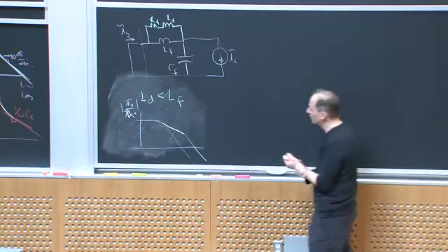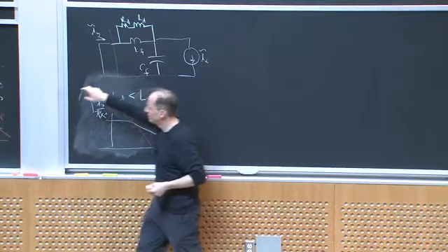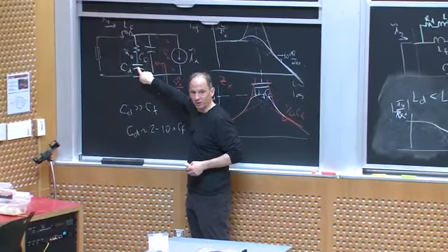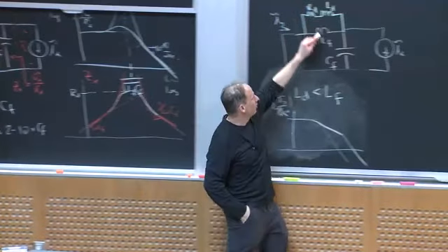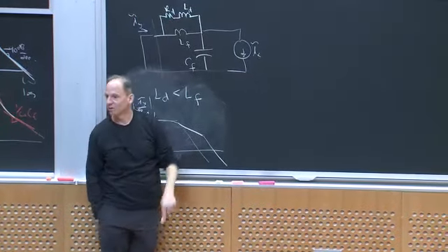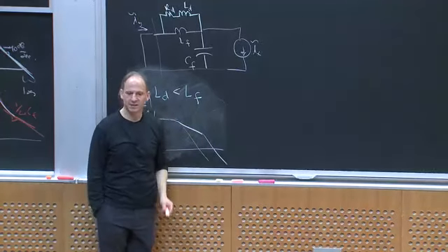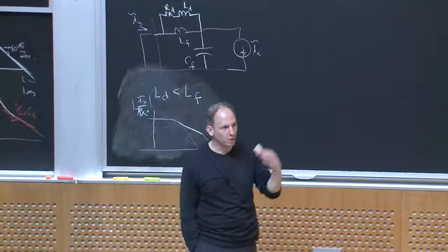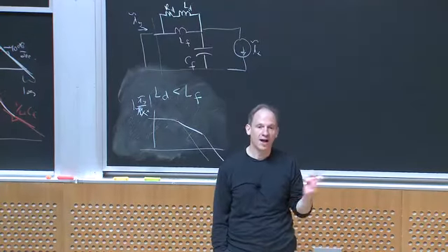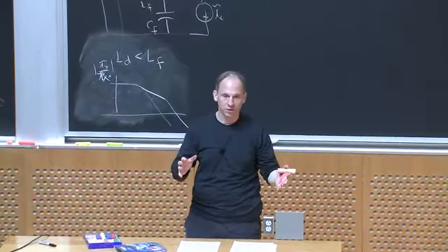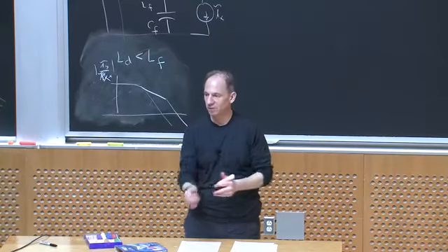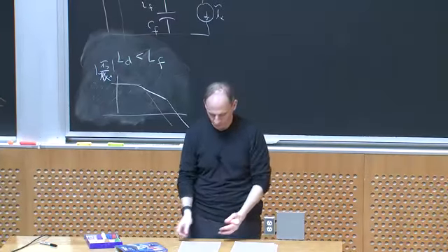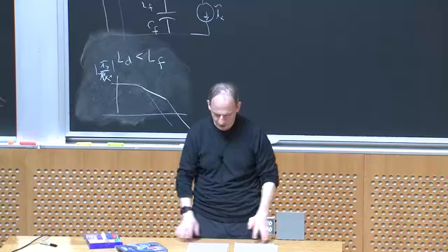The upside to the inductive damping scheme is that whereas CD costs me a lot of energy storage, right, because he's got to block the full input voltage, LD is small and carries no DC current, so he can be a pretty small inductor. Okay? So they both have their upsides and downsides. They're both widely used. Just depends on the situation. Try them both out. In one of the handouts I provided, I've actually shown all kinds of different filters, some higher order versions than this. But typically, an LC filter as a building block is a pretty good structure. Okay? Any questions about that?